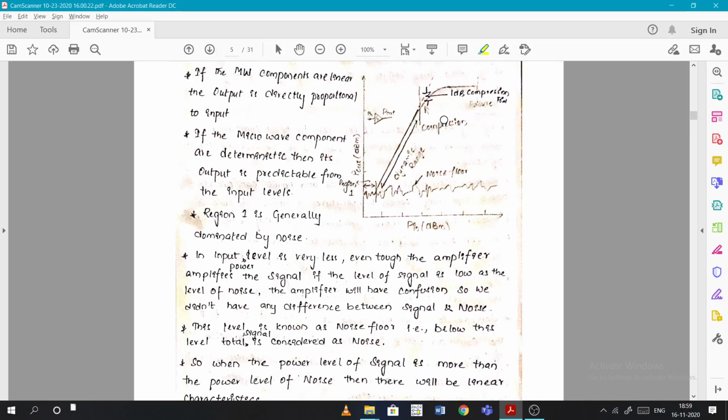So now coming to this, we defined this range and also this minimum range. So what is this linear range? This linear range is called the dynamic range. The dynamic range is defined by the maximum point at which it can handle, because after the 1 dB compression it is deviating, that means it is not able to handle the linearity. So that is the highest point, which we call P naught. What is the minimum point? Up to this point it is noise only, no? So this point is called N naught.